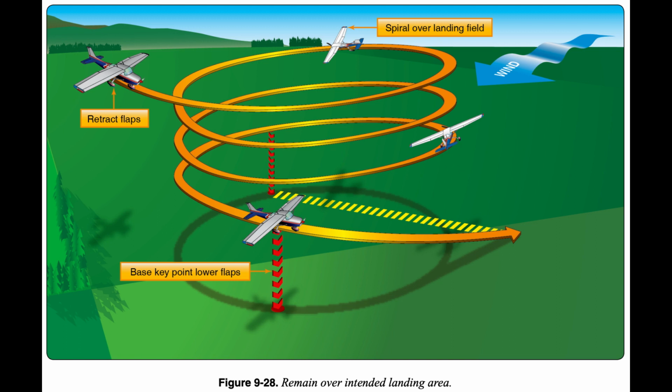the existing situation. A constant gliding speed is usually maintained because variations of gliding speed nullify all attempts at accuracy and judgment of gliding distance and the landing spot. The many variables, such as altitude, obstruction, wind direction, landing surface and gradient, and landing distance requirements of the airplane, determine the pattern and approach procedures to use. The pilot may use any combination of normal gliding maneuvers, from wings level to spirals, to eventually arrive at the normal key position at a normal traffic pattern altitude for the selected landing area. From the key point on, the approach is a normal power-off approach.